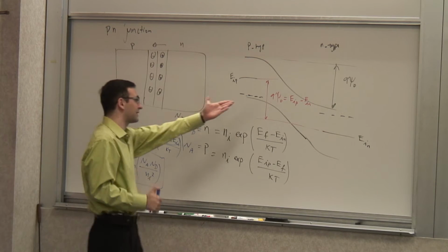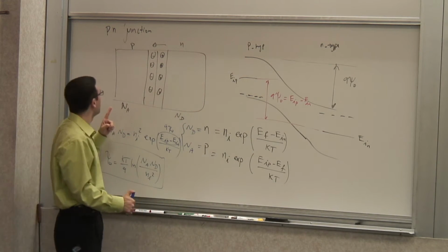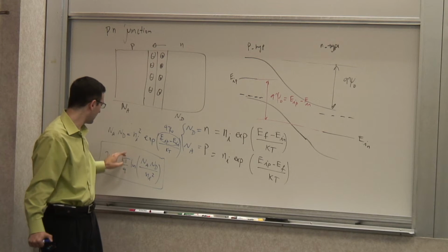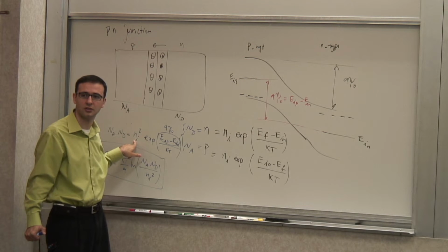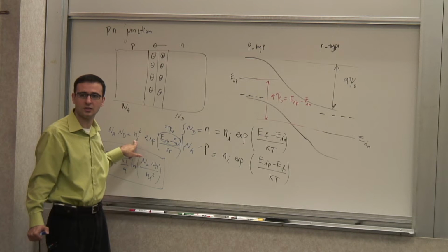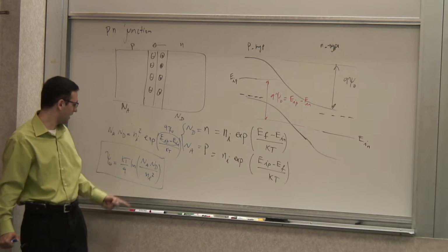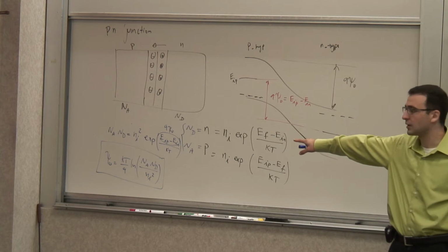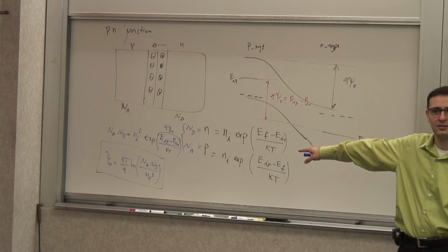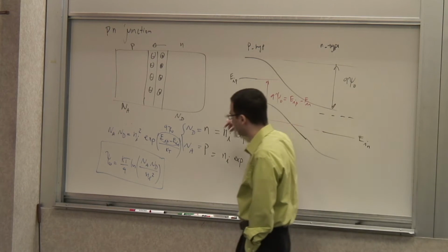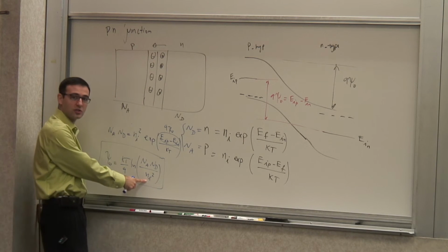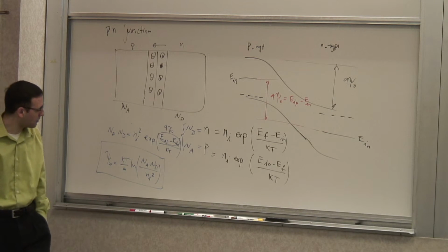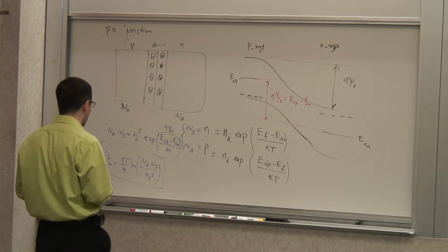So if I ask you what is the delta potential, you can easily calculate. All you need to know really is the doping level for the P side, doping level for the N side, intrinsic carrier concentration in the semiconductor. These are the three things you need, and the rest of them, of course, you know. Okay, and then of course you need to know what temperature you're at. And you can see there's a direct relationship to the temperature. Even from that expression, you can see as you raise the temperature, this goes up, but of course this one changes too. This is a strong function of temperature, because this is temperature reduced. So you have to take it into account. Okay, so that was the built-in potential, and that's fine.